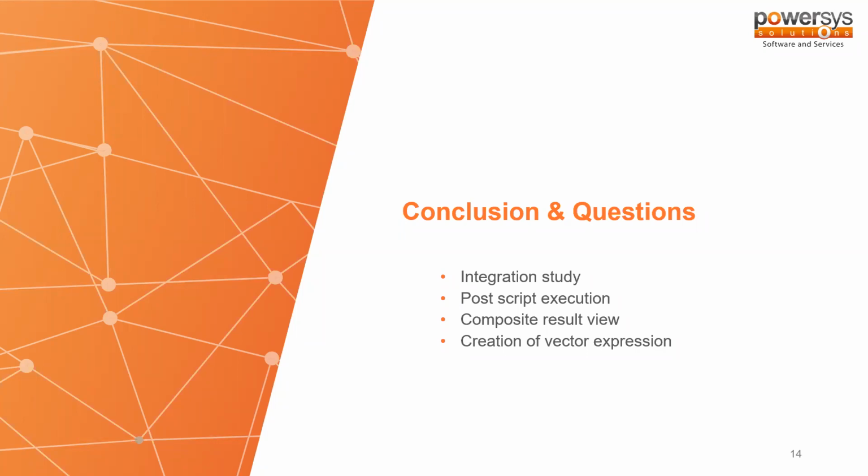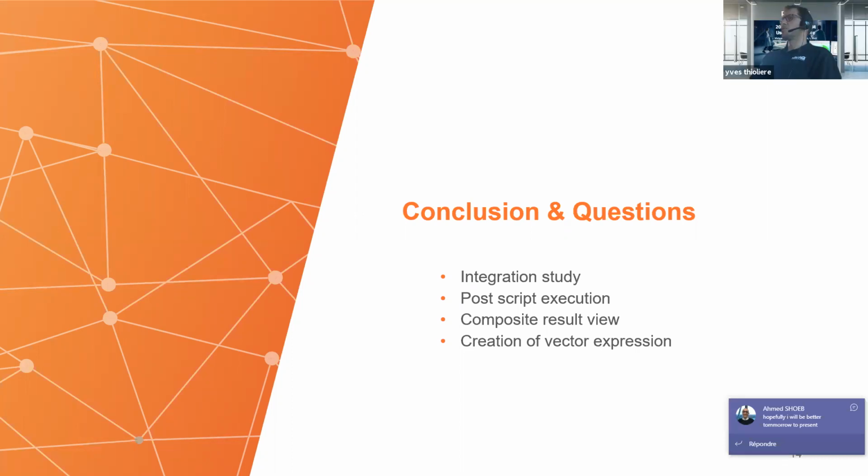In the efficiency map generated by Designer, how is the voltage limit taken into account? There is an algorithm in the JMAG efficiency map feature. First you run some calculation points, and then in the efficiency map creation you need to specify the DC voltage limit, and JMAG will search for the points working for this DC voltage limit and create the map that way.